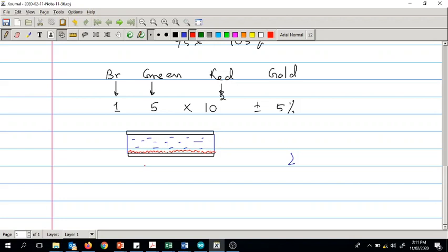So in that case, two properties, epsilon A over D. Let's assume that A is not changed. Epsilon is much higher. It's a property of the oxide. You select the material such that that oxide gives you a very good dielectric, and the thickness between the two plates is also much smaller. So what will you get then? A very large capacitance, right, for the same size.